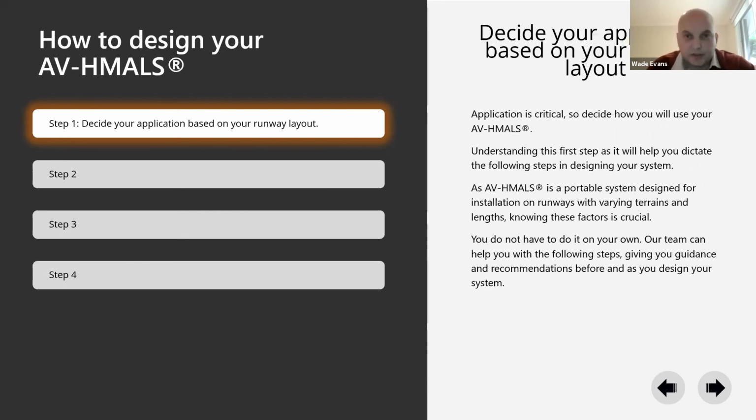So application is absolutely critical. What terrain is it going to be utilised? What is the length of the runway? What's it being used for? And what aircraft are going to utilise that deployment?